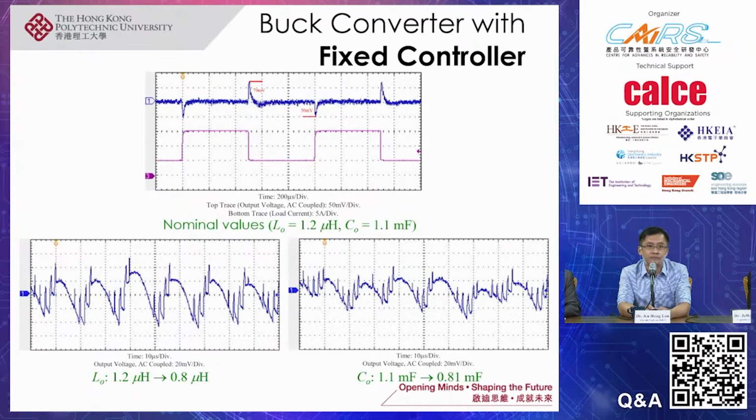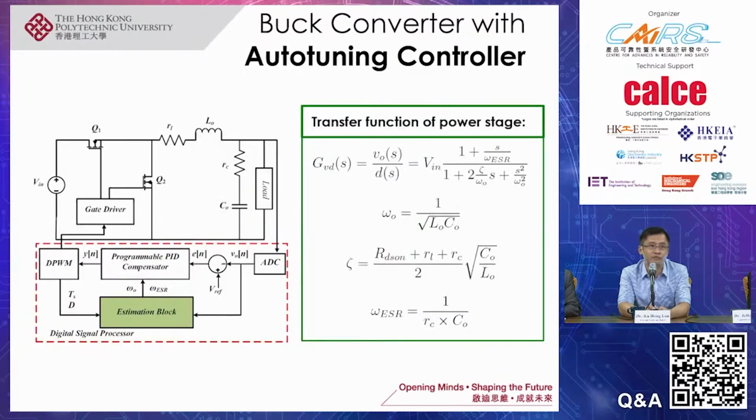This is a situation that we can commonly see in real DC-DC converters, because mainly the output capacitors of a DC-DC converter would be electrolytic capacitors. As they age, they will slowly lose capacitance. When they lose capacitance up to a certain point, then as the experimental results here show, this situation can potentially destabilize a buck converter.